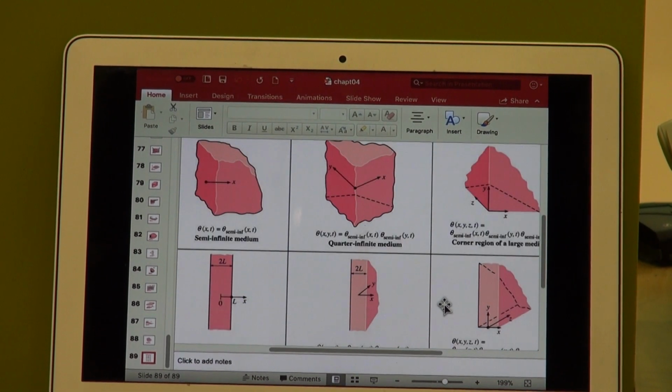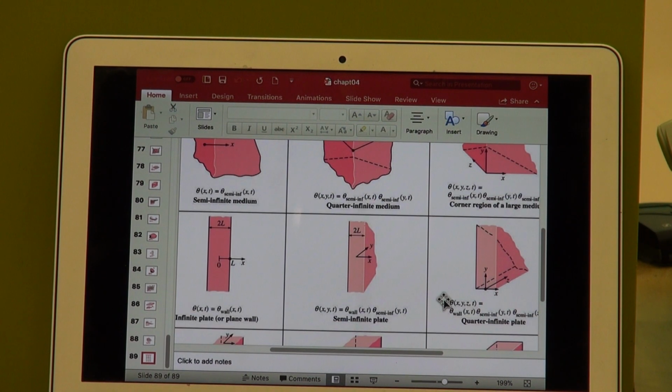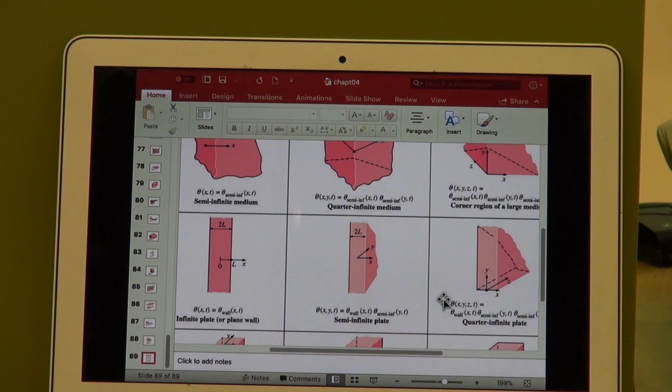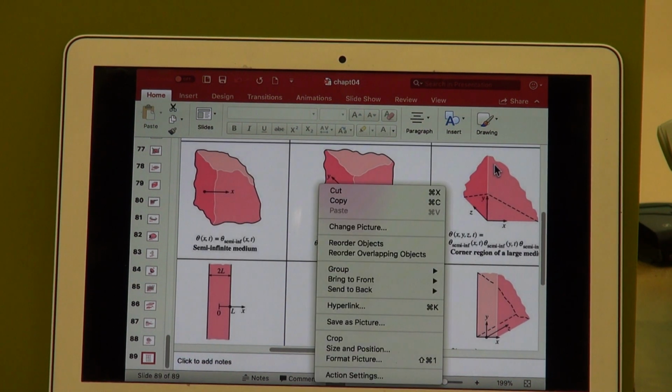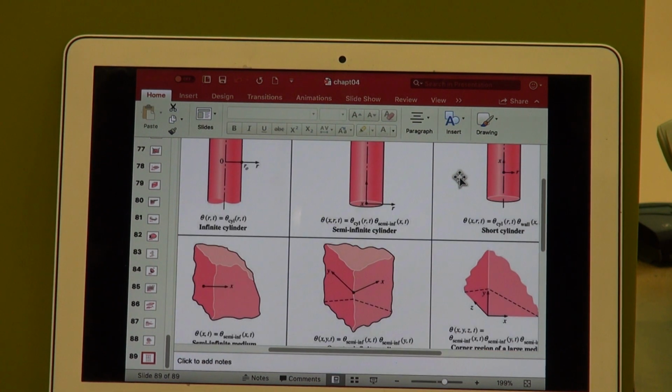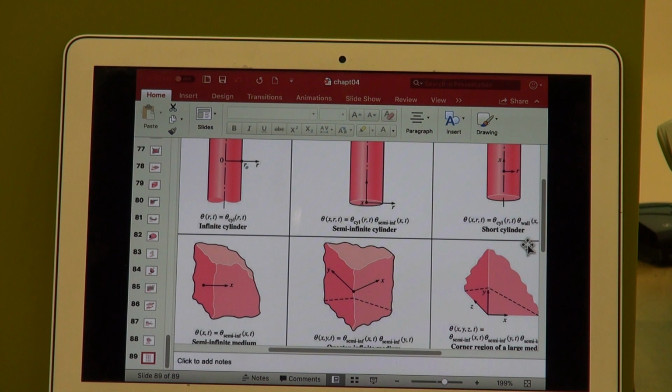Now, what is actually the secret or the most important thing to remember when you would like to use these types of solutions? It is to go and look very carefully of where the coordinate system has been placed. Where the coordinate system starts from, ends with, is extremely important, because that solution, if they tell you, typically it's the solution for a cylinder, then you need to go and use the equations that has been used previously for a cylinder.